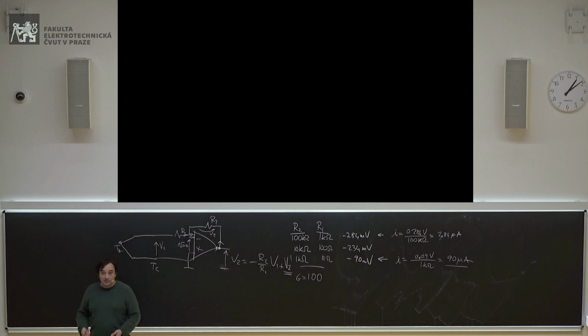You have to take some numbers, make sometimes some estimation of the quantity you expect. They don't need to be so precise. When I calculated the bias current here, I got 1 nanoampere, might be 4, but you know, it doesn't matter. You make some ballpark number and you calculate more or less how much is the effect. If you see that it's in the same order of magnitude, then you can try to make some more precise calculation. But if you see that the effect is several orders of magnitude smaller than what you observe, then you don't need to make very precise calculation. You just realize that it's too small to justify what you're seeing. Okay? So this is very important.